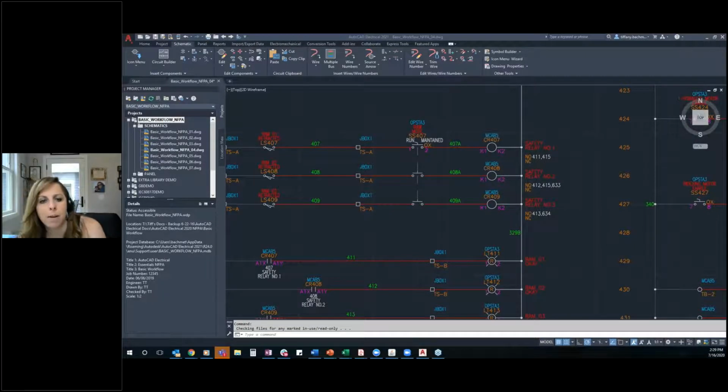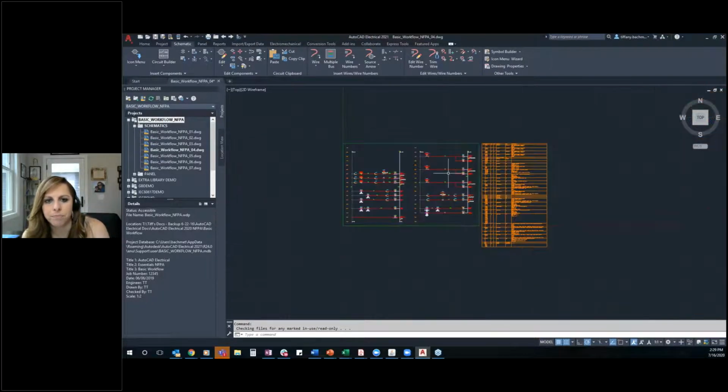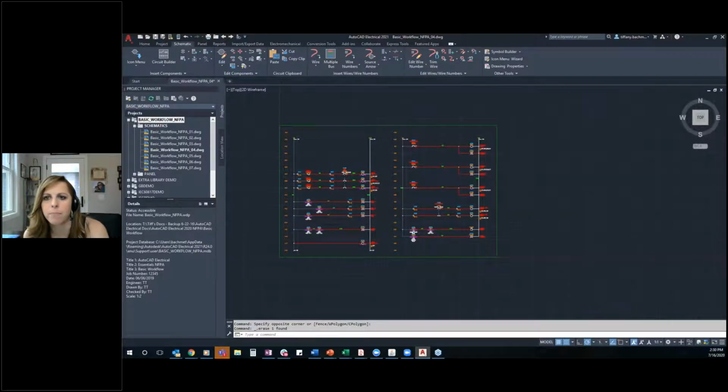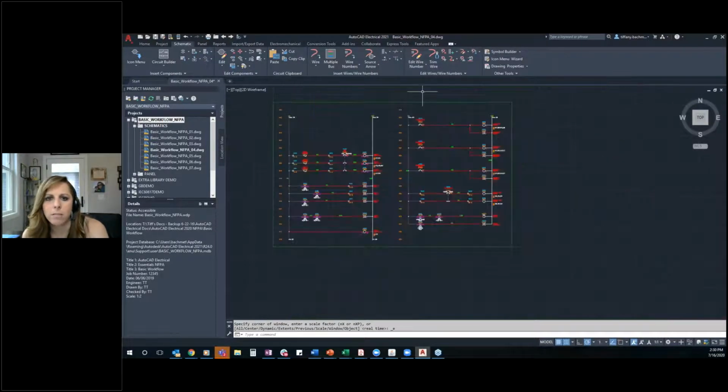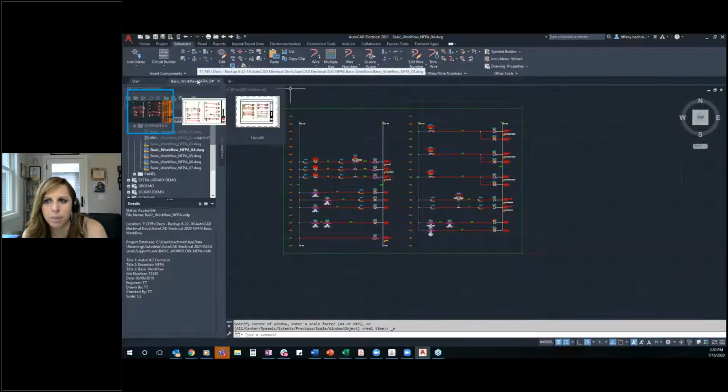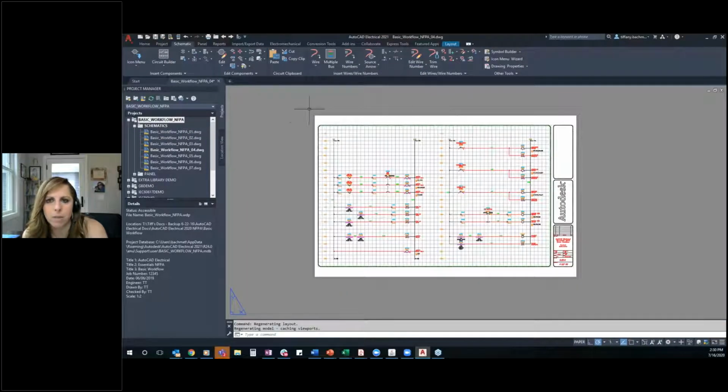So if you see on my drawing here, and let's just get rid of this, it was an add-in that I just threw a report in there so people could see it. So I have a rectangle that shows me basically a general location of where I want to keep my drawings, which is a lot of the argument for putting templates in model space so that you can see where you're drawing. However, this is more D-size to me to be able to get the 1-inch line spacing that I want. Now, if my typical plot is actually on a B-size print, if I go to my layout tab, you'll see that this paper is actually set up to be exactly that.